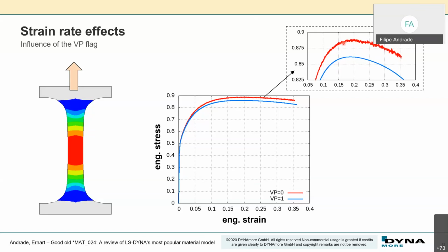In the case of VP3, which I don't have here today, basically, if you don't set the filter, you get a solution which is quite close to VP0. And if you start using the filter, you can get rid of this oscillation a little bit. And if you really push it to the limits, at least for the uniaxial tensile test, you can even reproduce the solution with VP1, which at first glance always looks like, okay, VP3 can be like VP1.